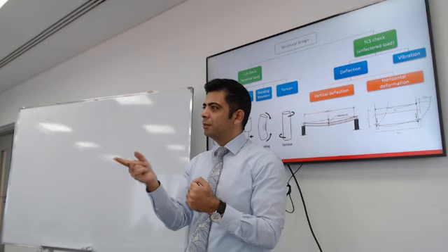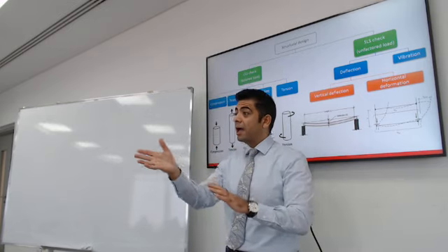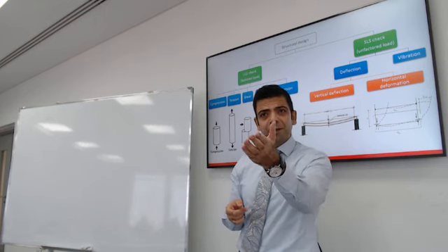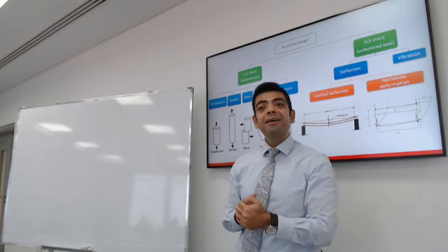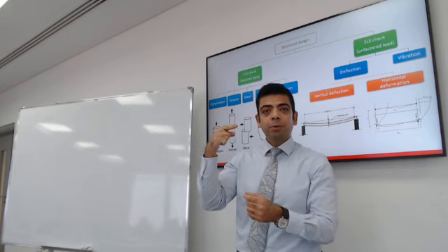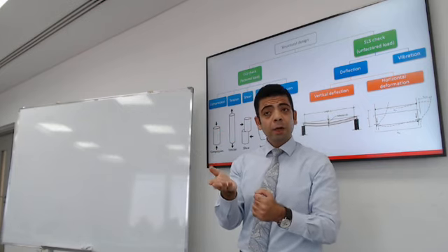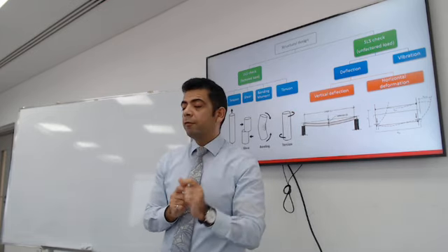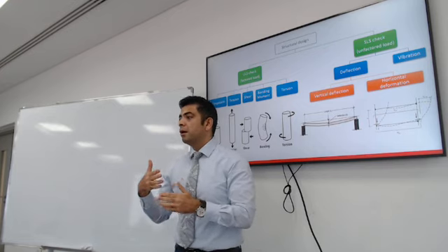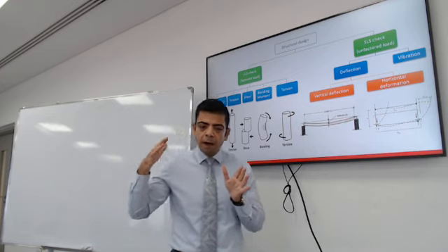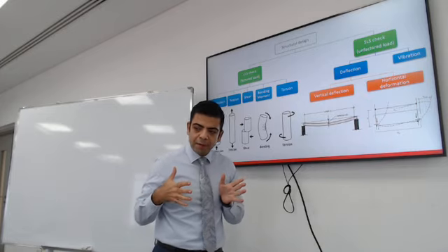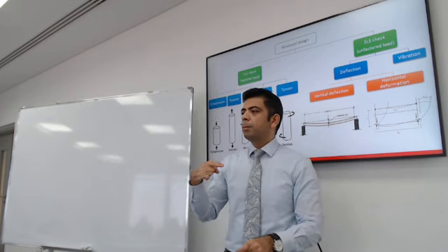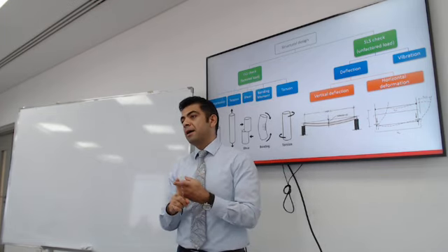So what would be the structure applied? Dams, bridges. Okay, that was the example I was going to go to. Do you have a thought? I said natural disaster. Natural disaster would put a horizontal force, like earthquake. For example, tornadoes, tsunamis. Okay. There is a very common force on bridges when big heavy vehicles slam the brake. All that friction will be transferred to the bridge as a horizontal force, so braking force. That could be an example.